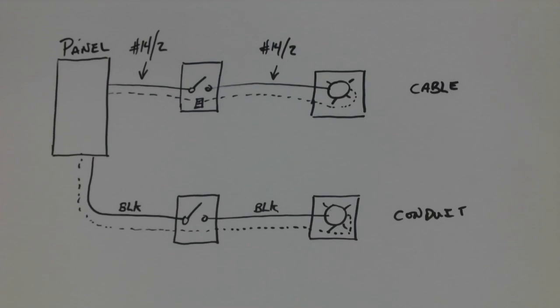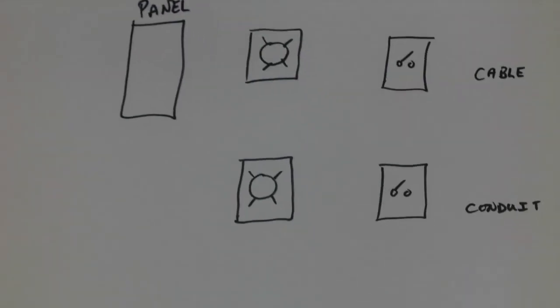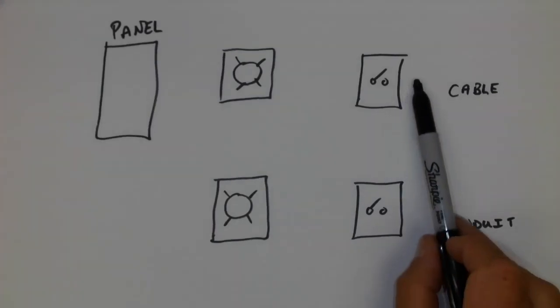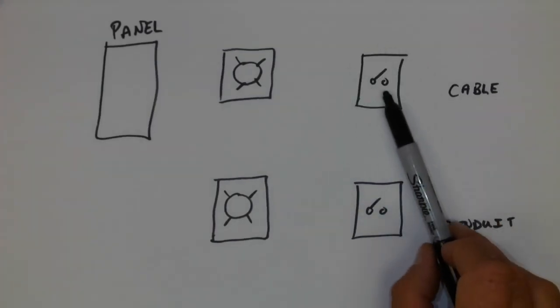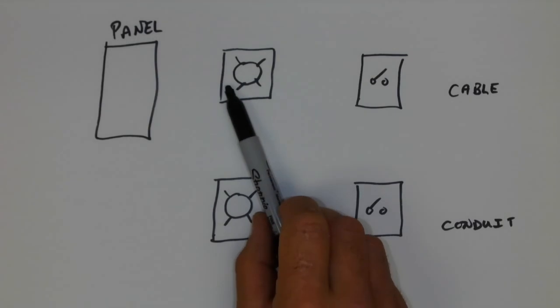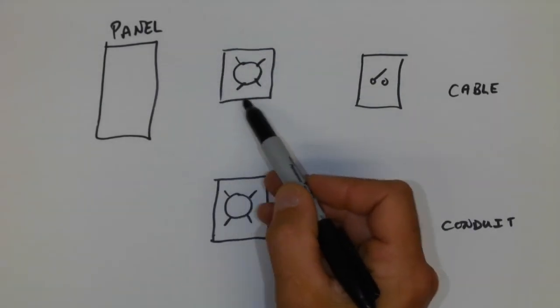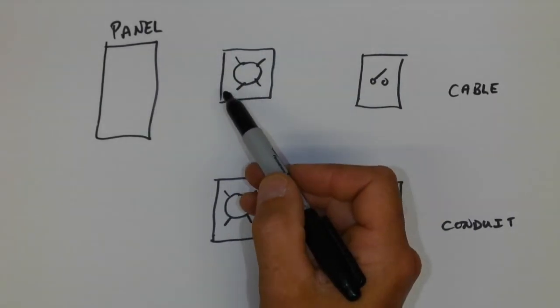Now, other types or variations of this were found in pre-2018 installations, and those centered around a type of installation called a dead-end switch. So this is the example of a dead-end switch. The dead end means the switch is at the end of the circuit rather than at the very beginning. And the method we would use to install this would be to make a splice in the lighting box.